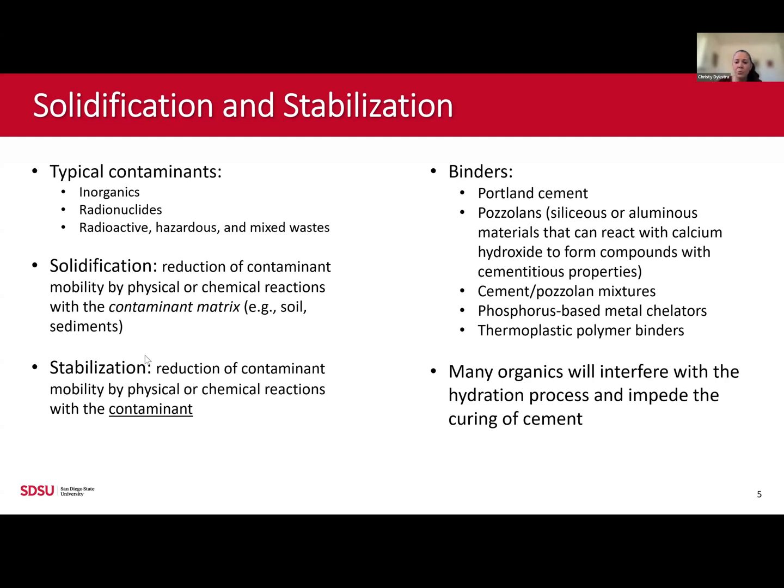Now, we do have to keep in mind that a lot of organics will interfere with the hydration process and impede the curing of cement. So this can be a challenge, especially if you have a lot of organics in your soil or in your sediments. And so that has to be considered at the site where you're trying to do either solidification or stabilization.